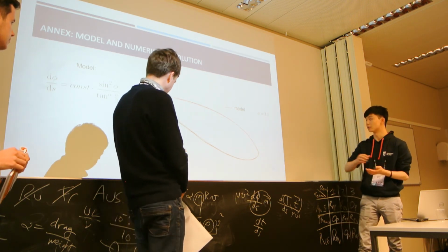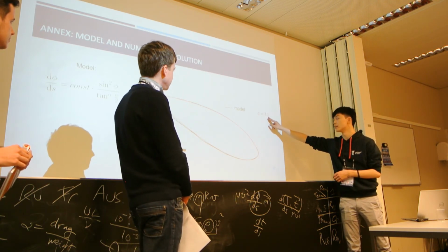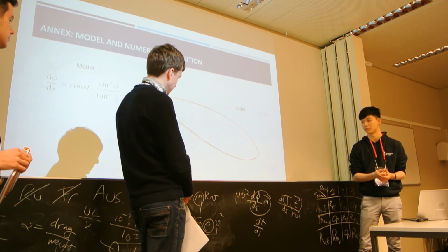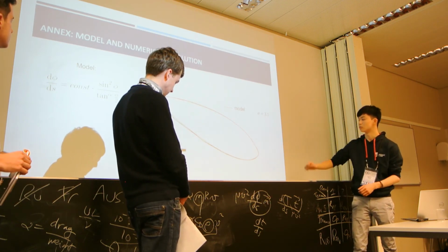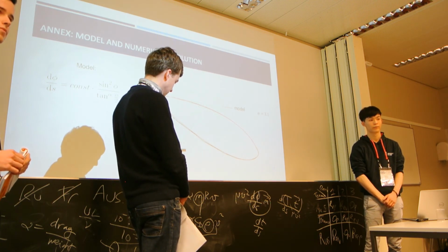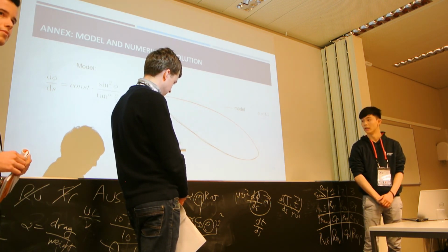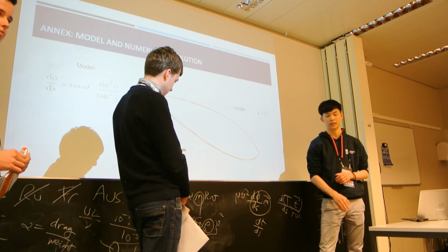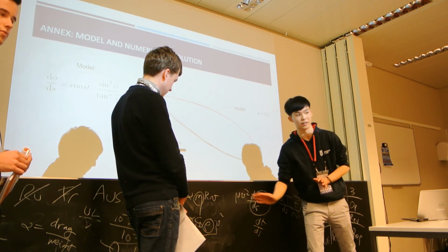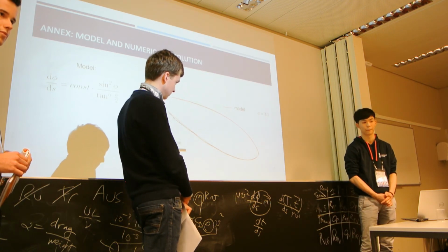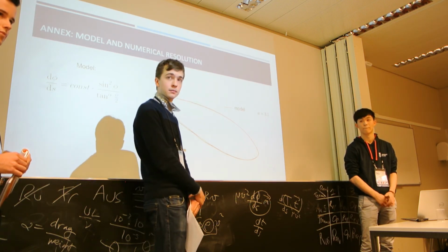You can check if the velocity that you find with alpha is consistent with the velocity that you put into your system. This should validate if you're in a low Reynolds regime or high Reynolds regime. It's a bit complicated because in our model the drag is constant. So we treat this coefficient as a constant, so we can't know which formula is the better one.